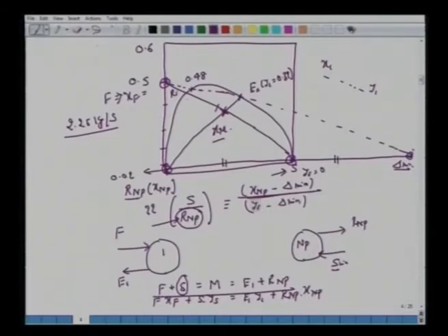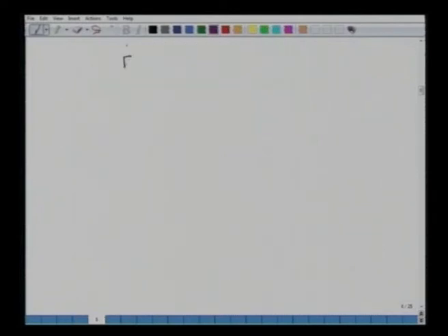That means now we can apply a tie rule. Say this location was F here for XF, and here we have S solvent, which is Ys equal to 0. If you connect this point here, we get this XM as 0.3.